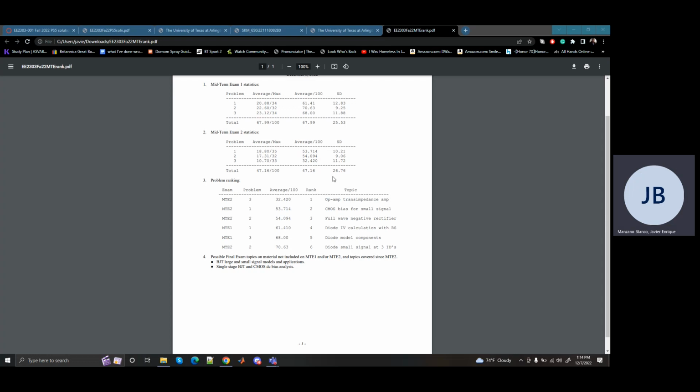V out minus V in, we're on just VR. That gives us current, right? That gives us the current flowing through R2 and R1 because no current's flowing into the op amp.